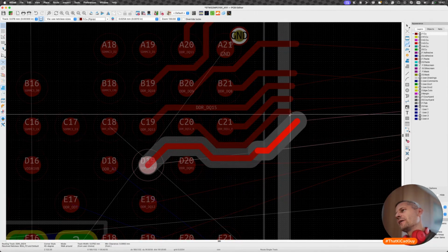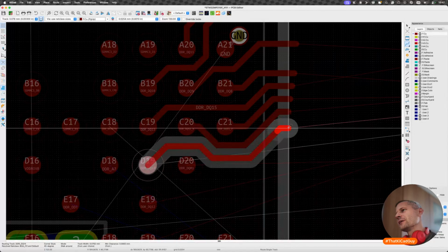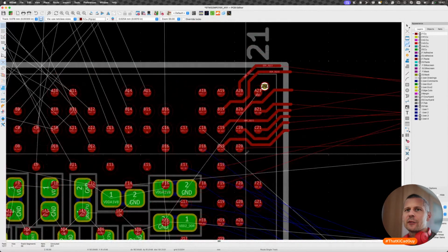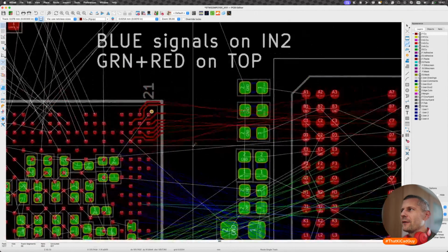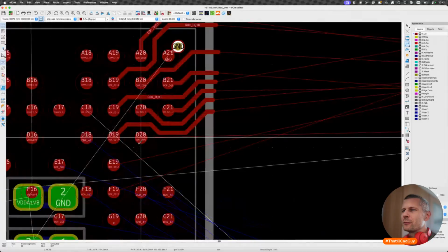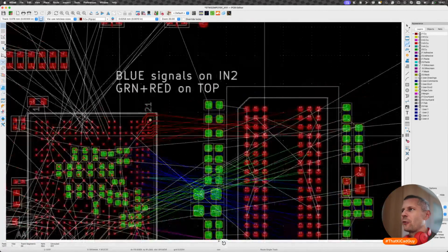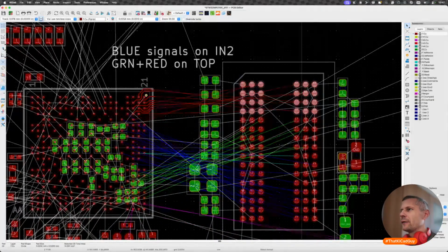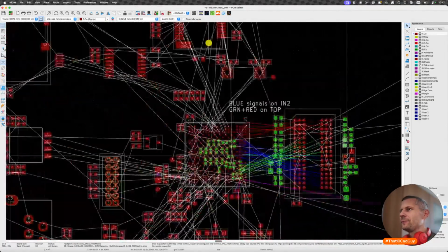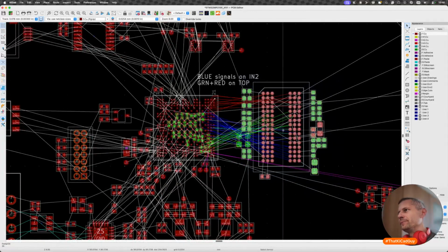I have to say that the fanning out of the signals is now much easier, because I care only about the color, not where the particular signal goes, because I know that this position offers that all the reds go to the upper side and all the greens go here. I think maybe what we can do is to minimize the length difference, the expected length difference.